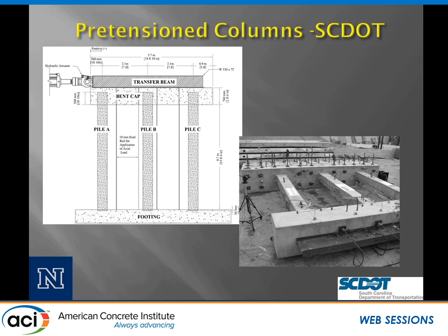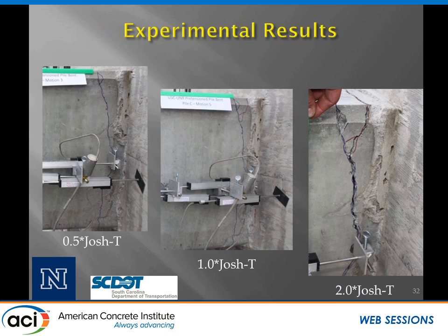And this was a relatively large scale. The piles were actually cast in South Carolina and shipped to us. And then we just racked this frame back and forth in order to study its overall behavior. I don't have time to go into a lot of detail on this one, but we saw that the pile itself stayed fully connected with the cap beam. It never separated from the cap beam. And we did see some cracks that were opening up at this interface. This is at 0.5 of the design level, this is at the design level, and this is at 2 times the design level earthquake. So obviously we have a large crack here, but we had overall very good performance even though the thing was just stuck into the cap beam.